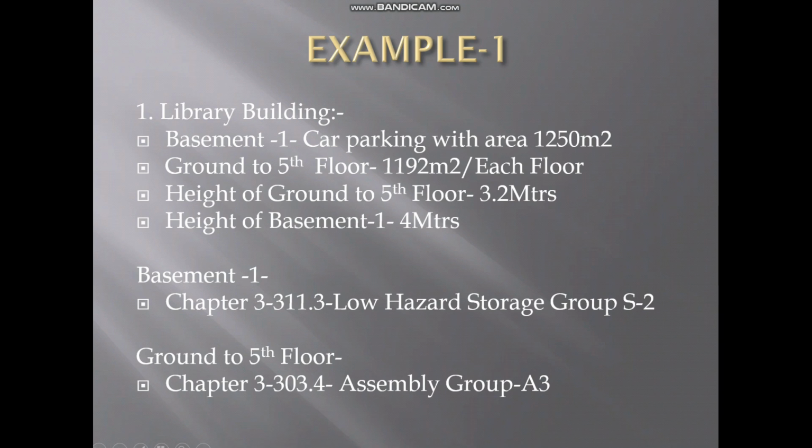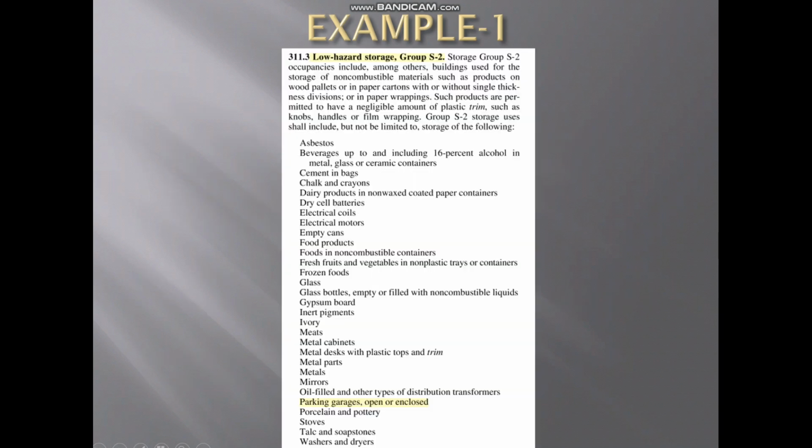So for basement 1, let me open the occupancy groups. Basement 1 is a car parking, and car parking comes under parking garage, open or enclosed. It comes under low hazard group S2.